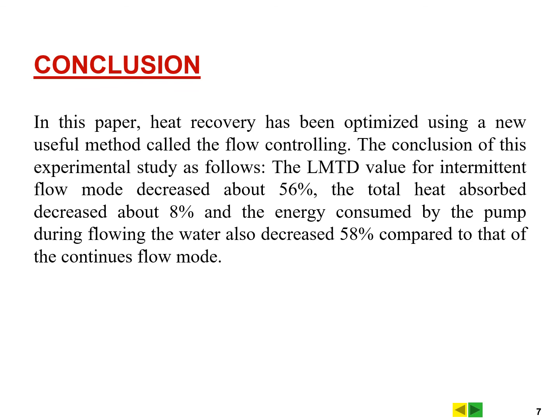Okay, let's continue with the conclusion part. In this paper, the heat recovery has been optimized using a new useful method called flow controlling. The conclusion of this experimental study is as follows. The LMTD value for intermittent flow mode decreased by about 56%. The total heat absorbed decreased by about 8%, and the energy consumed by the pump during flowing the water also decreased by 58% compared to that of the continuous flow.